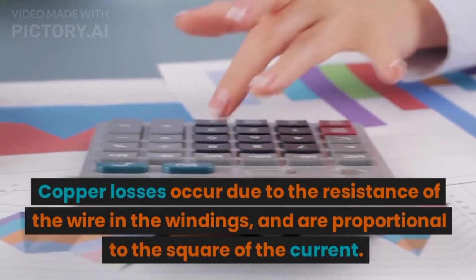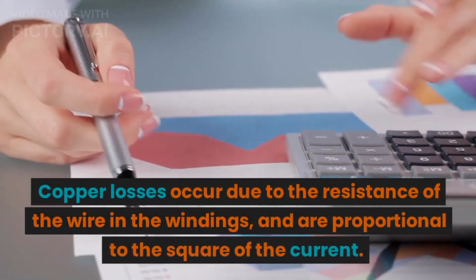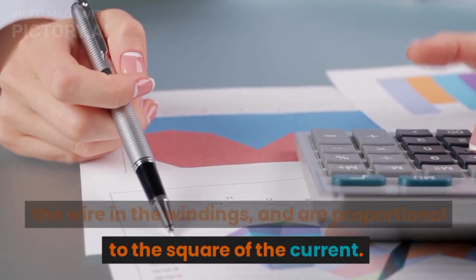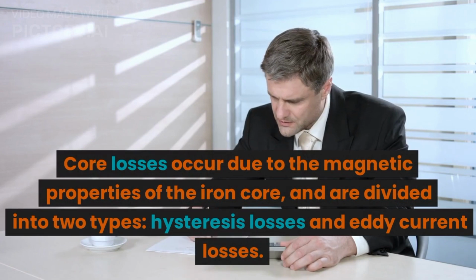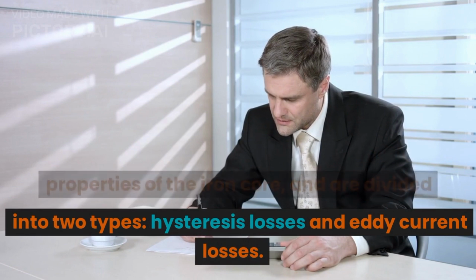Copper losses occur due to the resistance of the wire in the windings, and are proportional to the square of the current. Core losses occur due to the magnetic properties of the iron core, and are divided into two types: hysteresis losses and eddy current losses.